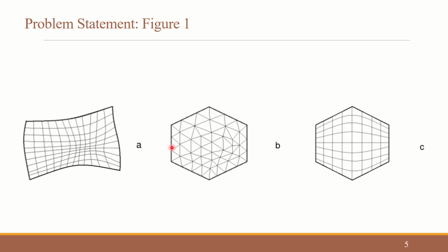Whereas in 2, if we say I equal to 1, I equal to 2 in the x direction, we are not very sure which I we are talking about. That is, I equal to 0 here, 1 it can be here or here. Again 2 it can be here, here or anywhere. We cannot give a structured way. So this one is a structured mesh. This one is an unstructured grid.